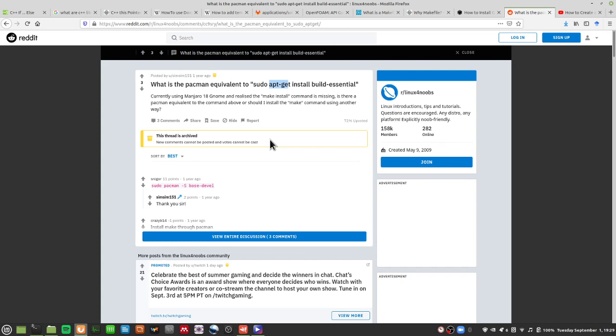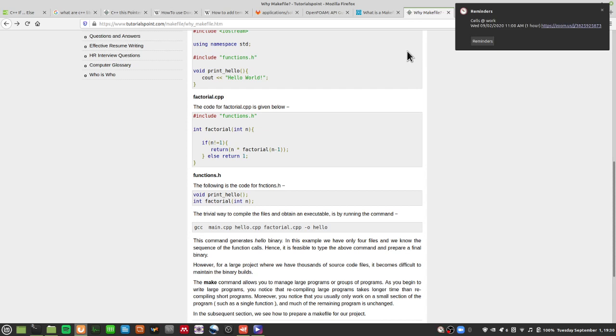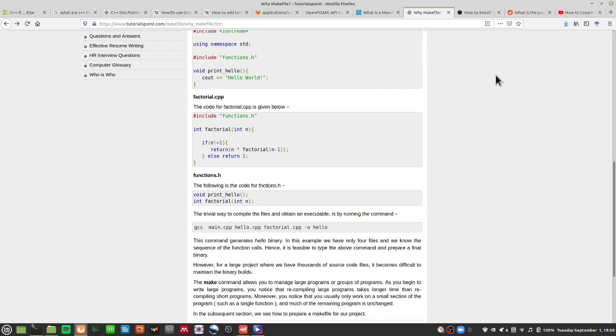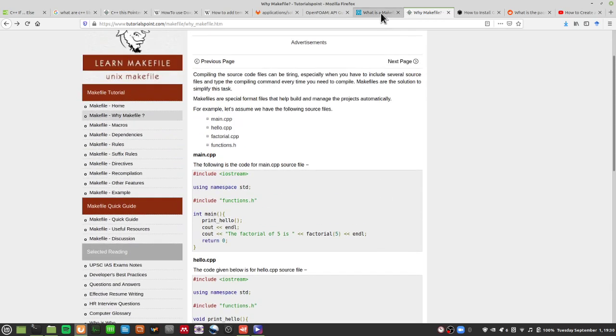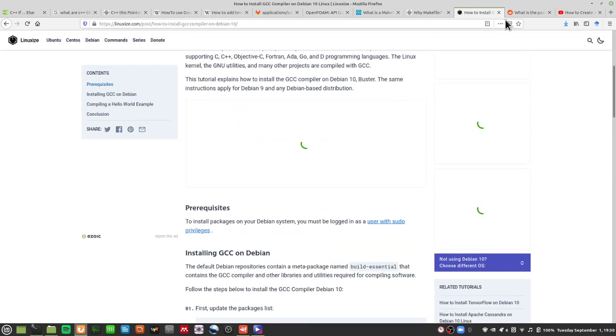Anyway, that's kind of redundant. That's if you don't happen to have make installed. Honestly, if you install OpenFOAM successfully, you will not need to bother too much about this. This is just in case it's not working properly.